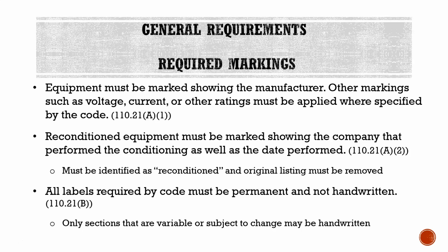So in the panel in your home or dwelling, you likely have a schedule that tells you breaker number 1 is for the kitchen, breaker number 2 is for the master bedroom, breaker number 3 is for the living room or the den. The reason they give this exception to this rule is because later down the road you may move around some of the breakers in that panel or change some of the circuit numbers, to where now circuit number 1 is for the guest bedroom, circuit number 2 will be for the kitchen, and so on and so forth. So we want to be able to easily change those as needed.